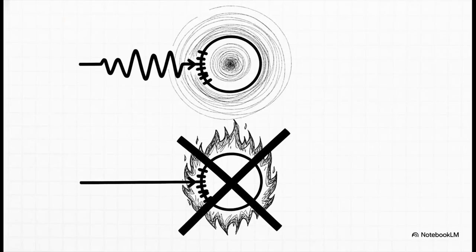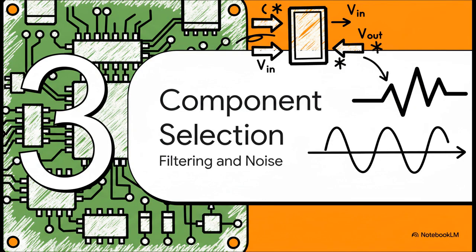Okay, actually, listen up, because this is a fundamental rule that catches so many beginners off guard. Transformers do absolutely not operate on steady-state DC voltages. Remember how they need a changing magnetic flux to induce voltage? Well, steady DC current gives you zero change. So if you accidentally hook up a primary winding to a DC supply, well, your inductive reactance drops straight to zero. Without that impedance, you get a massive instantaneous current surge that will literally burn out your copper component. Please don't do that.